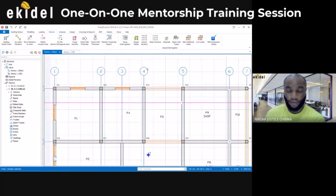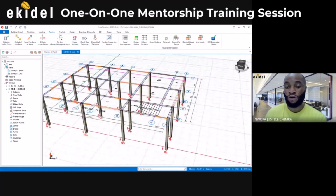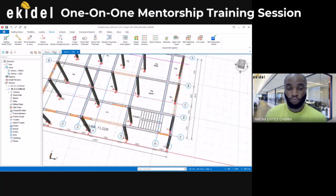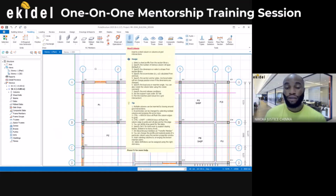Okay, that's fine. So once you've done this, the next thing is to begin our beam insertion, because now we only have our columns and the grid lines. So come back to plan view here. On the plan view now, we'll go to the Modeling tab. On this Modeling tab, we have the concrete section area and the steel section. So you can see column here and column. This one here is for concrete and this is for steel. And we are dealing with the concrete section.